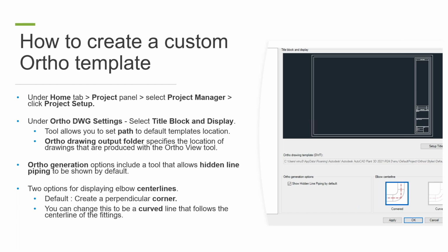Now, once you've created the ortho drawing, going out and modifying the template won't update that drawing, of course, because templates are only used for creation of the new drawings. So you would have to then add extra geometry or whatever to your ortho drawing itself, or recreate that ortho drawing anew, because the template is used once to initialize that ortho for the first time.